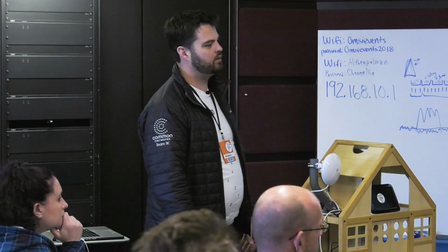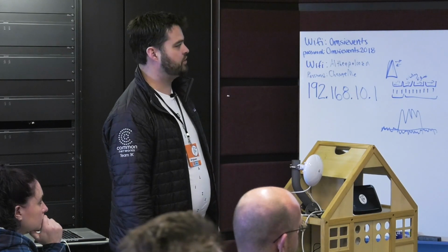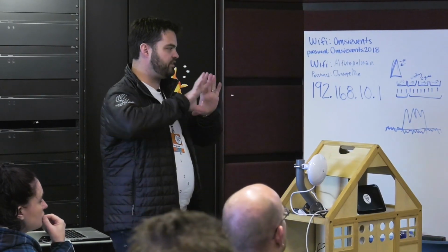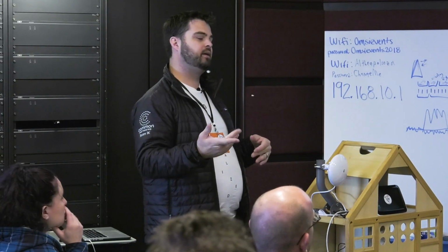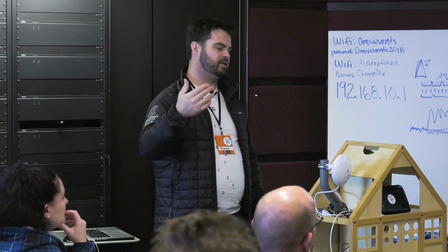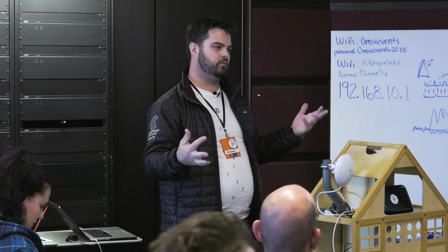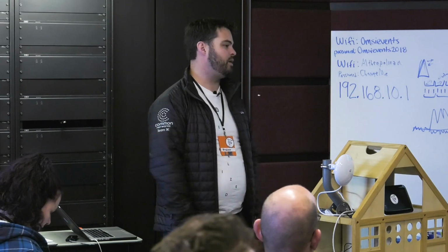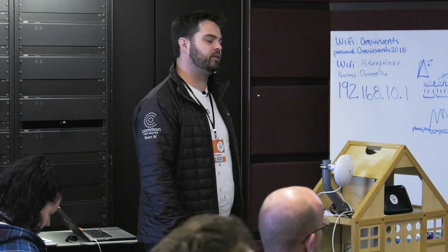Does it impact signal strength? Yeah, question. So does the fiberglass covering impact signal strength if you're trying to shoot through it? It does. It can. What I understand is that it can be as low as a dB or 2 of loss, which you have to account for, but can maybe still be manageable for what you're trying to do.